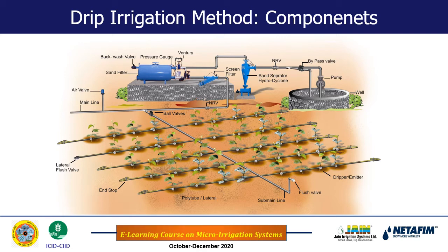Okay, so for that the certain diaphragm arrangement is made inside the PC dripper, for which we have to pay extra. The cost of pressure compensating emitter is more, and at the same time we need extra care because of that diaphragm, we should have a very effective filtration system. Otherwise, by chance if clay particle enters into the PC kind of emitter, then diaphragm will be damaged and this PC emitter will no longer work as the PC kind of thing.